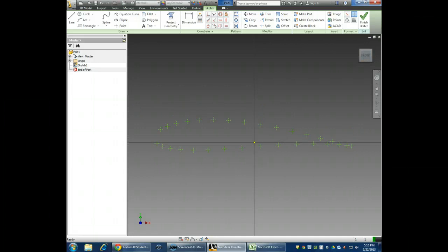You can kind of see it looks like my wing is, and I've got some other issues around here where these kind of run together. So I may actually delete a few more of these back here. My wing gets very, very thin near the end, and that would be a problem, especially when I do the 3D print. The last step would be I want to pick the spline tool, and the spline tool is going to want me to pick the different